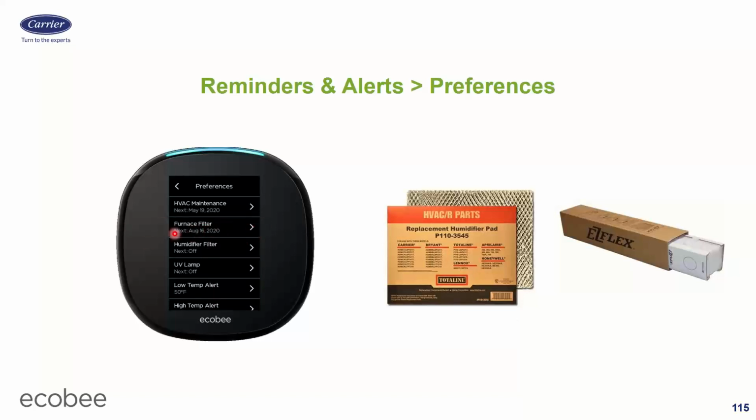I'm not a fan of these. I really like the ones we have in Infinity Evolution because it measures static pressure and tells me when the filter is truly dirty. I like that. I don't like fan timers for filters because, let's say I pick 3 months. Well, 3 months running in the winter is a lot more runtime than 3 months running in the fall because I'm running the heat a lot more, right? So I'd want to pick the hourly timer, but I just don't know how many hours it should be. So I don't really have a good gauge of that. So you can make these things work if you kind of massage them and play with them.